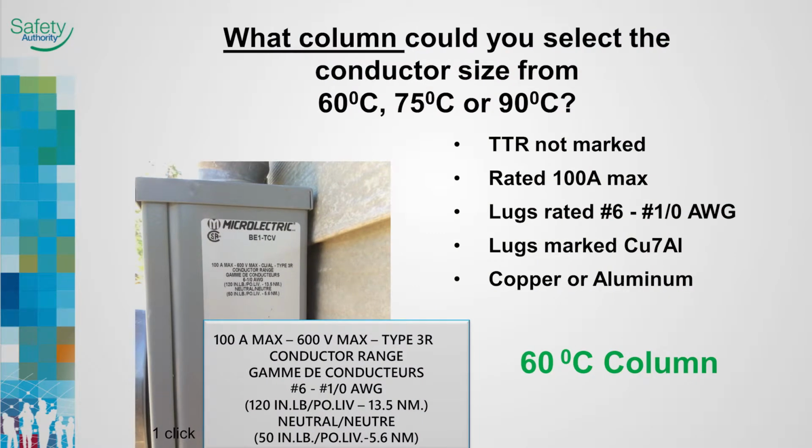If electrical equipment is not marked with the temperature termination rating, the TTR must be obtained from the manufacturer's specifications, or use Rule 4-006, Subrule 2 to determine the rating. Certification standards for equipment with lugs only, such as meter bases or splitters, do not require mandatory marking of the temperature termination rating. At this time, TTR is a voluntary marking requirement.